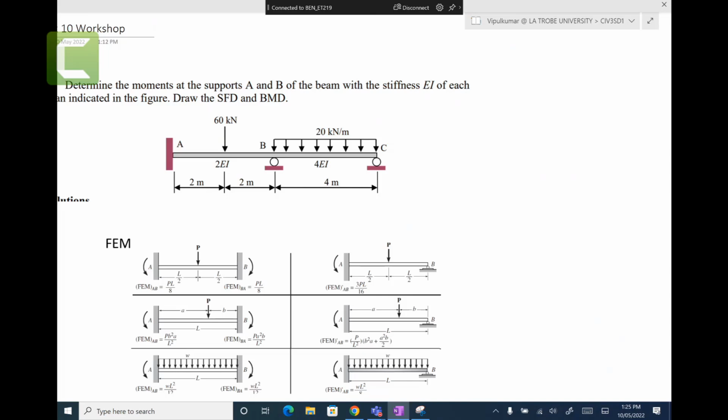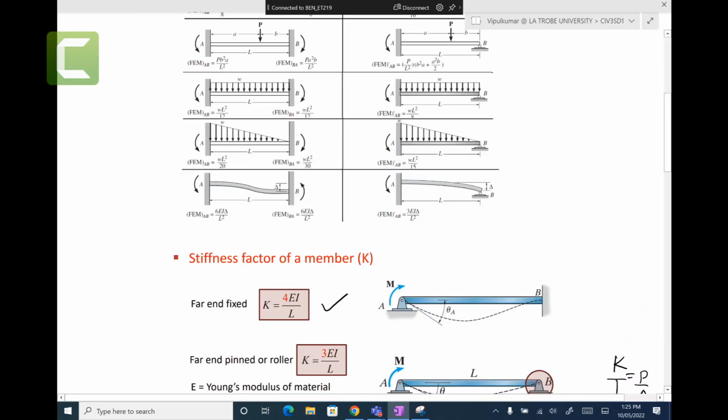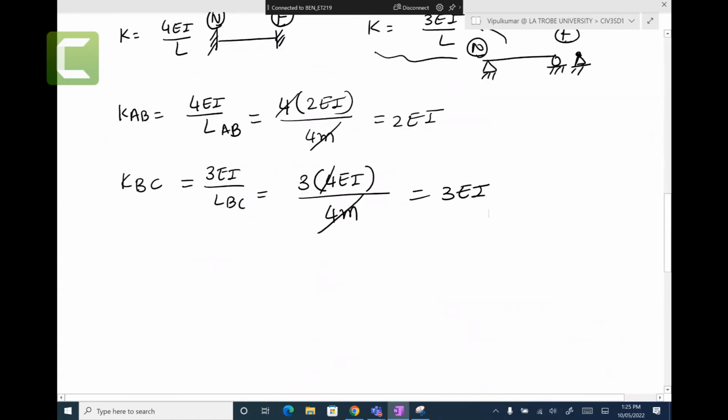Okay, that's the stiffness. And let's look at that. Stiffness depends on your EI value and depends on the length. The length is the same. Your EI is higher, so of course this will be stronger. So you don't need to just blindly follow. You just need to feel what is happening. So stiffness, everyone okay? Yes, please go ahead.